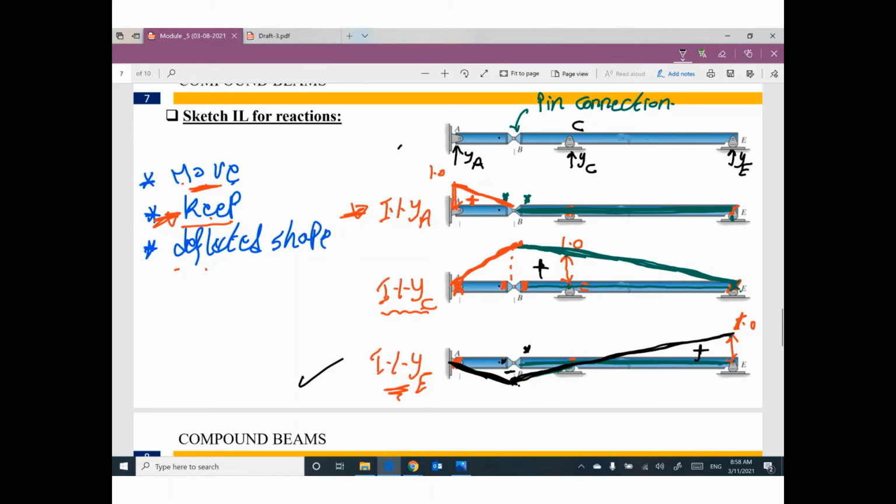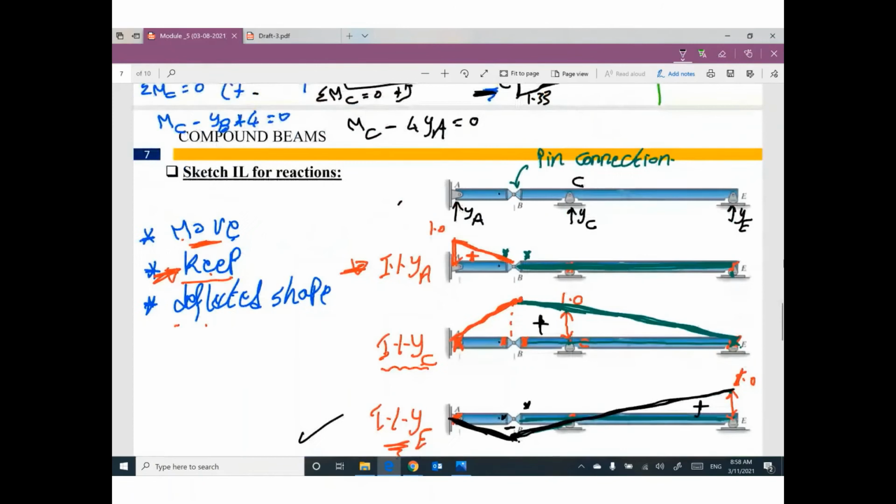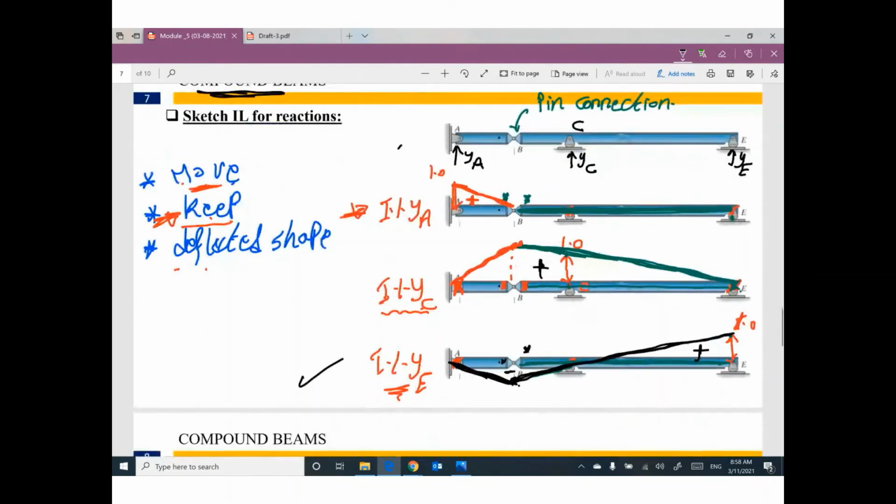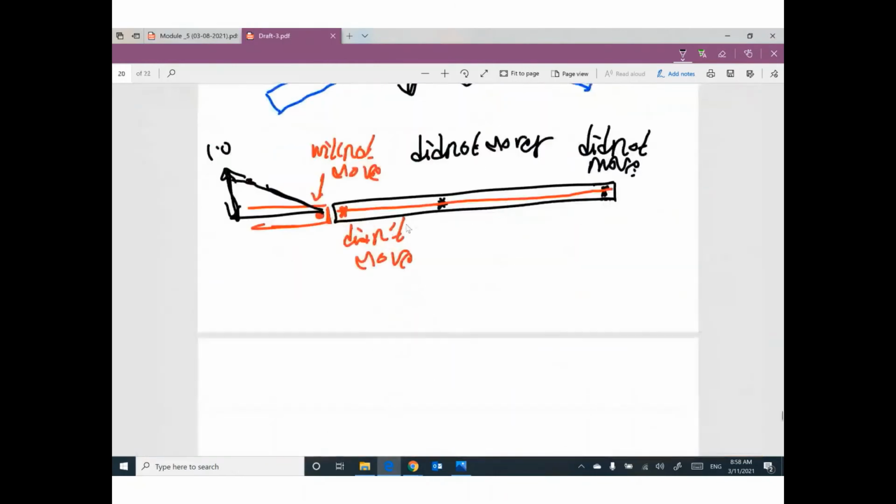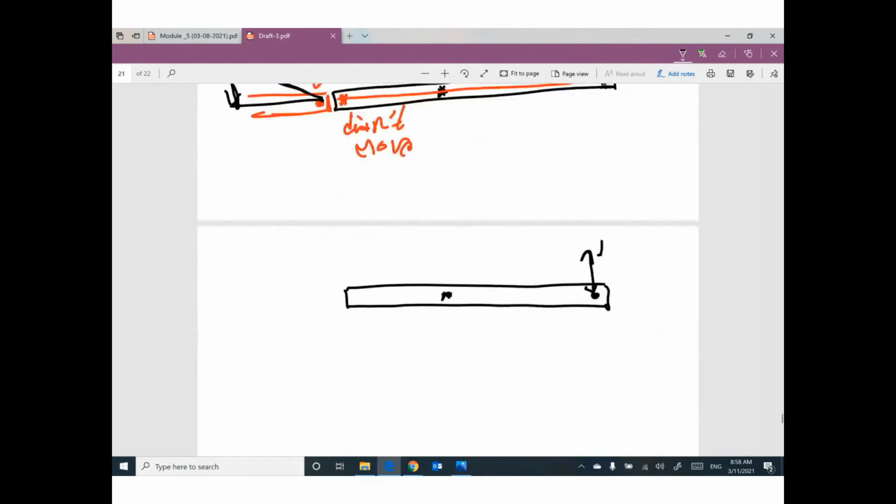Do you like this beam? So our beam started to be a little bit more complicated. But if you would like to draw influence line for reaction, you have to keep in your mind, if you have 1 piece of beam and you decided this point to move up and this point will remain as it is, the new shape of this piece must be straight, 1 unit.